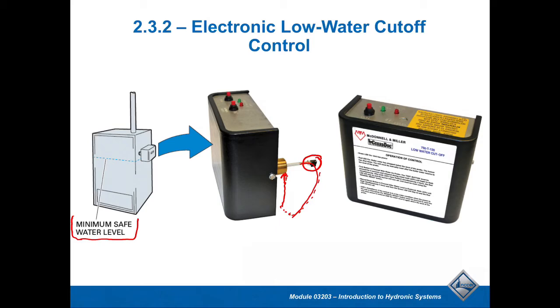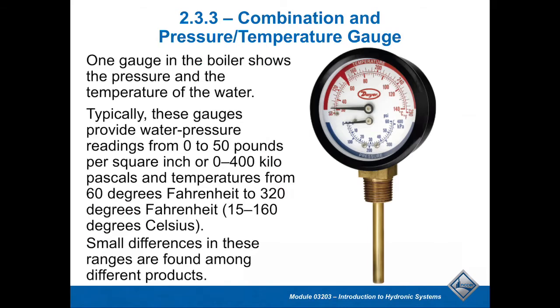So low water cutoffs are generally required on most of your commercial jobs and some of your residential jobs, depending on the municipality or where you're located. But that would be the idea of a low water cutoff. You don't want to run a boiler without water in them.